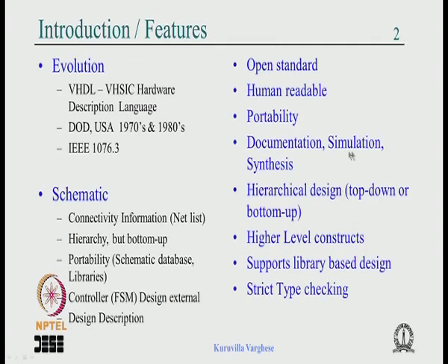And similarly there is the syntax for simulation. There are some constructs in the language which are only used for simulation, there is no point in using them for synthesis. So this should be kept in mind. It is not that anything you write can be synthesized. There are some things meant for synthesis, some things meant for simulation, and some parts of the language are merely meant for documentation. So don't complain too much.